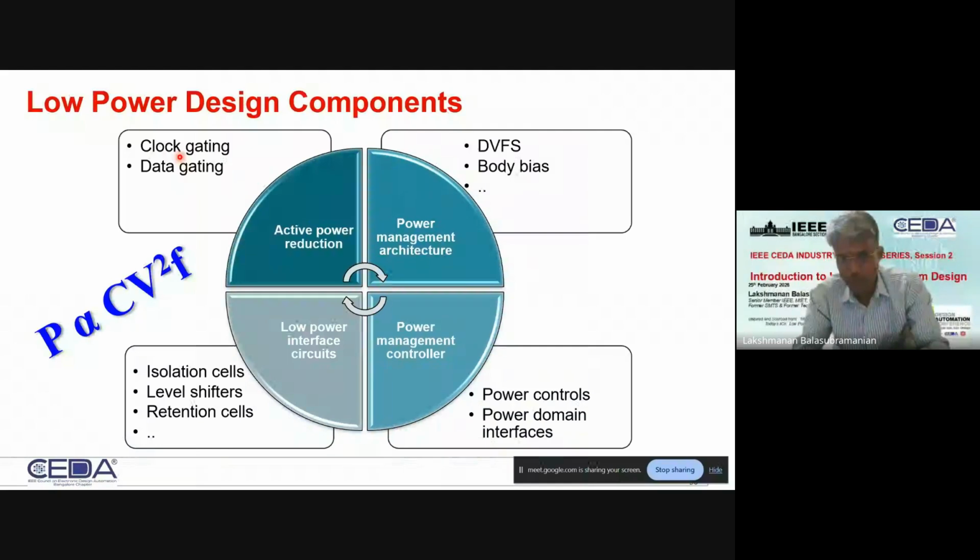I think as we go, we will also understand why, given the time, I'm limiting myself to a few critical aspects of low power design. Makes sense. Clock gating in general is very well known. Even before the low power design techniques evolved, activity gating, reducing the dynamic power consumption is very well known. I won't get into the details of that right now.